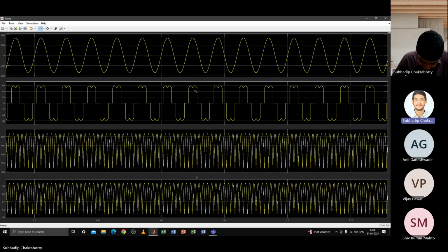If there is no shift in the fundamental, then sine of theta is 0. Then where are you getting reactive power from? No reactive power compensation is needed. Only harmonic compensation is required. Now, if you are a design engineer, in that case the current will be 0, sir. Current rating, which current? For providing reactive power compensation, the reactive component of current is 0, not the harmonic component.